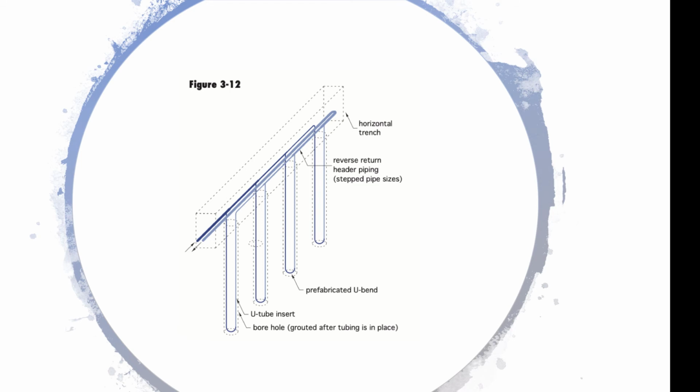The trench on the top is excavated by a backhoe, where all of the plastic tubing is fusion welded, and then eventually the supply and return loop ends up on the inside of the building. The joints on this type of tubing are typically provided by the loop field contractor and are done with polyethylene tubing and are typically a fusion socket weld or a fusion butt weld type of joint.